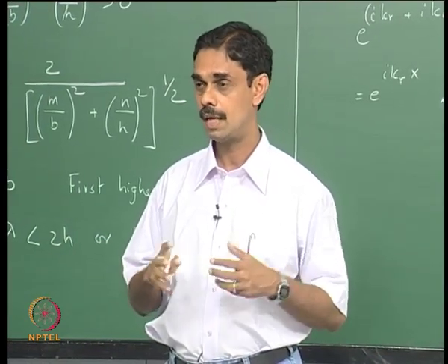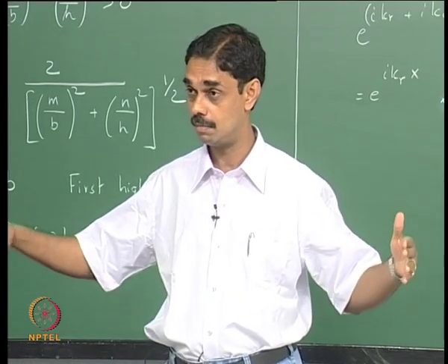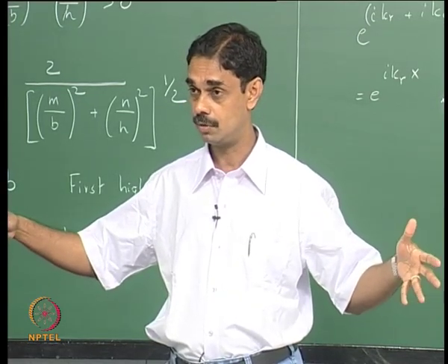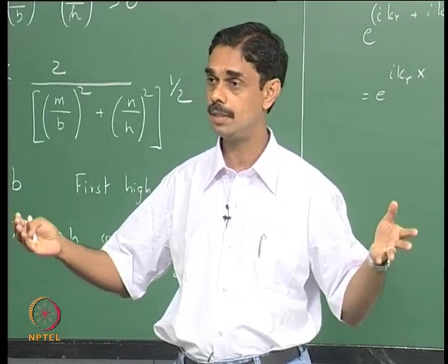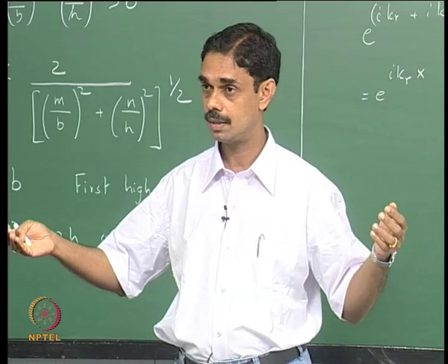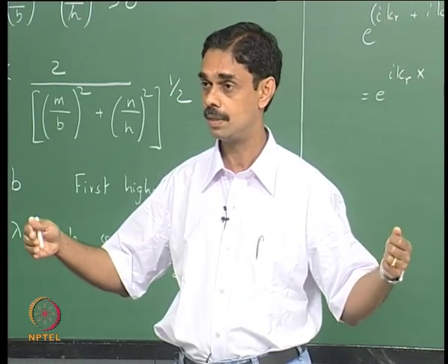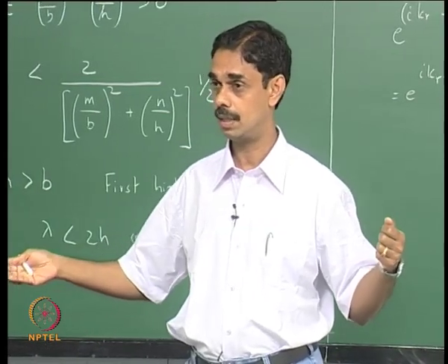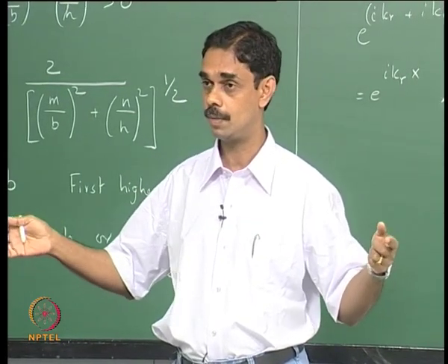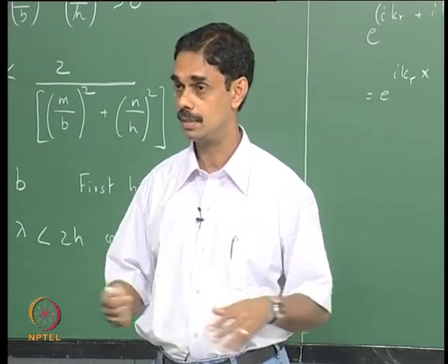This is as opposed to an eigenvalue problem, where we prescribe conditions at the boundary and then solve for the frequency and the wave number. The relation between omega and k is the dispersion relationship. In an eigenvalue problem you will get a dispersion relationship, where you can say omega over c equals k, and omega can be complex, k will also be complex, but c will have to be a real propagating speed.